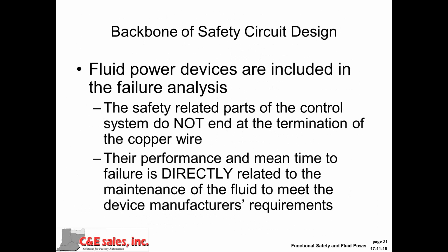Need to remember that fluid power devices are included in the failure analysis. I've seen another application where the controls people have said, well, no, we don't do the fluid power. That's somebody else's job. It is very definitely the safety-related parts of the control system don't end at the end of the copper wire. They go all the way to the control of the hazardous device, cylinder, motor, whatever that might be.